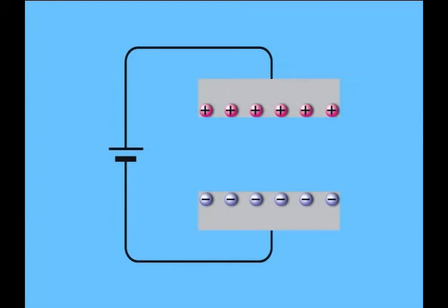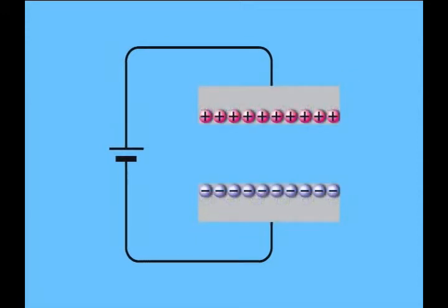While external appearance and structure may vary from capacitor to capacitor, the basic structure can be represented by a pair of electrodes. When voltage is applied between these electrodes, the electric charge accumulates on the surface of the electrodes. The larger the surface area of the electrodes, the larger the amount of electric charge that can be stored. The narrower the distance between the electrodes, the larger the amount of electric charge that can be stored.